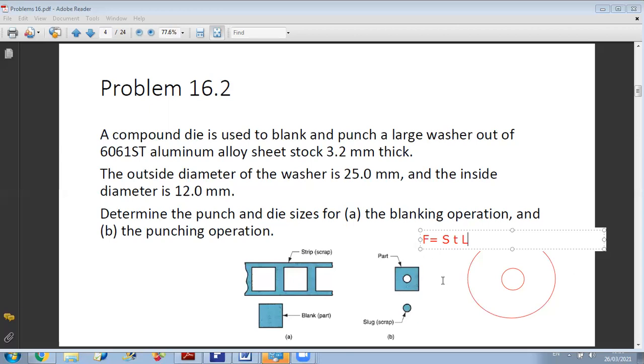Okay, so here first you have that the material is the same for both. You have the thickness is the same, so the criteria will be the length. So yes, Karim. As Karim said, if we perform the two operations at the same time, the required force will be higher. Why? Because you can see here that the force is proportional to the length of cut.